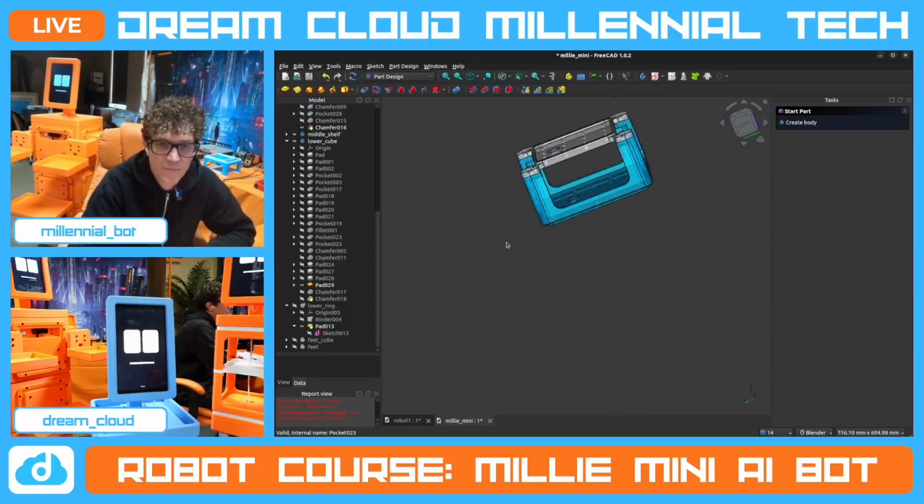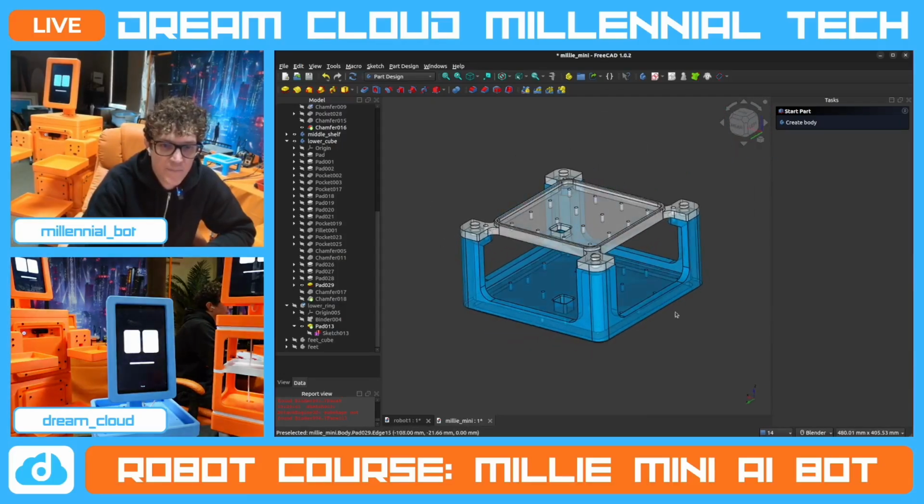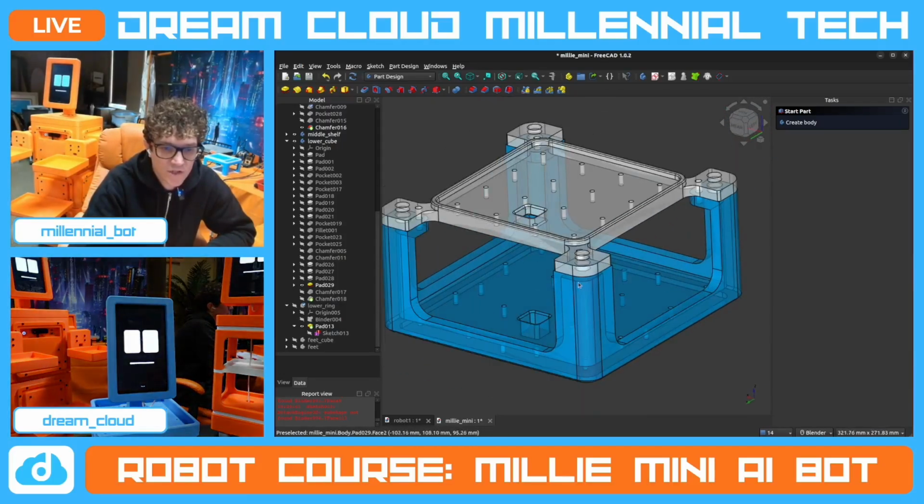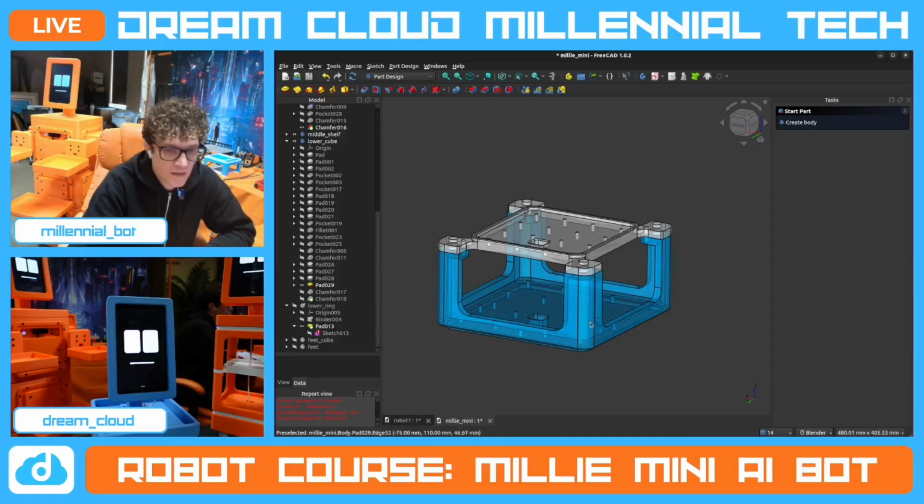So if you create something that will align pieces like that, for this project, we're gonna separate the arms. I think it would be a good idea to print just this lower pad right here as one piece, and then we'll create, I'm sorry, not arms, but these are like the vertical components. We're gonna re-engineer this so these vertical components are individual and they'll bolt on individually. And then you'll have this middle deck, and then you'll have more vertical.